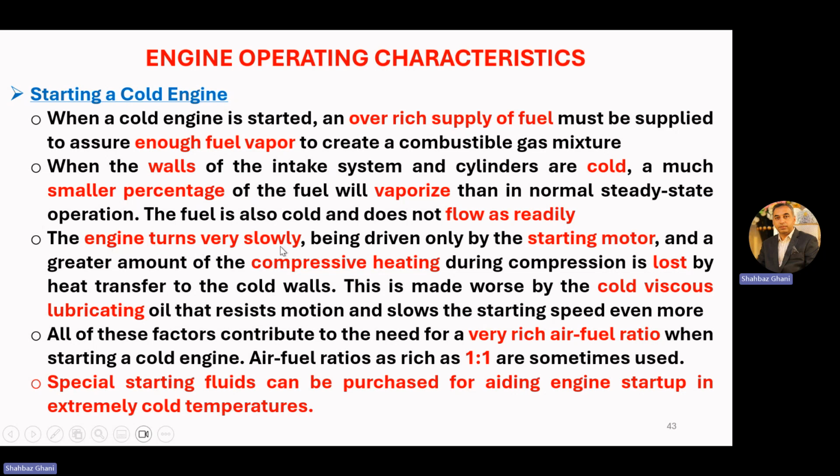The engine turns very slowly in cold starting, being driven only by the starting motor, and a greater amount of the compressive heating during compression is lost by heat transfer to the cold valves. So almost 70 to 80% of your compressive heating, and sometimes even more, is lost during compression to heat transfer to the cold valves. This is made worse by the cold viscous lubricating oil.